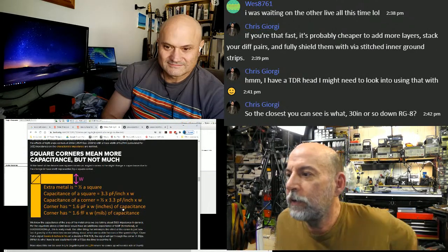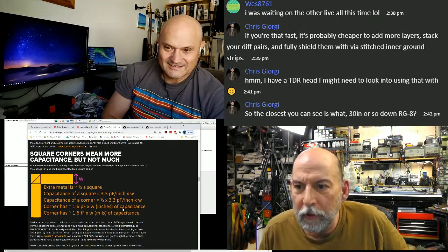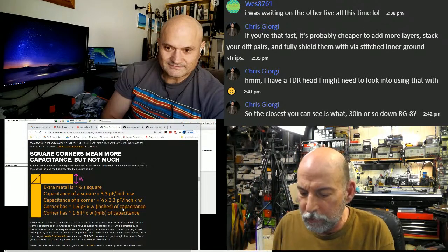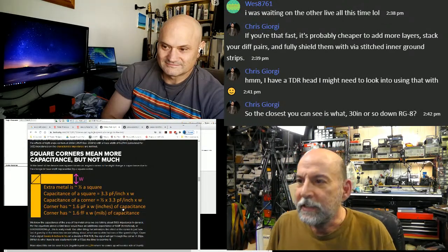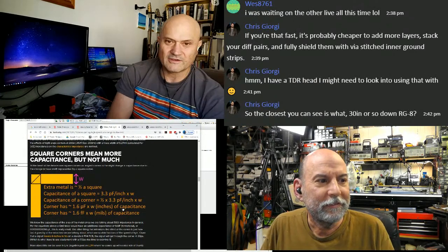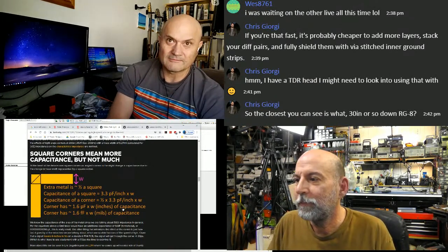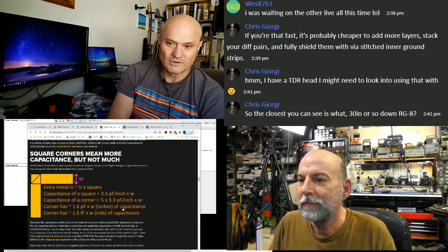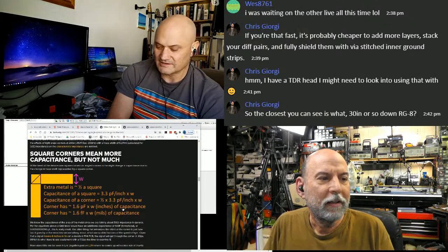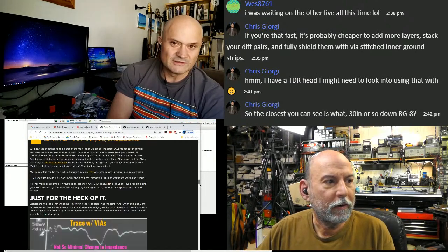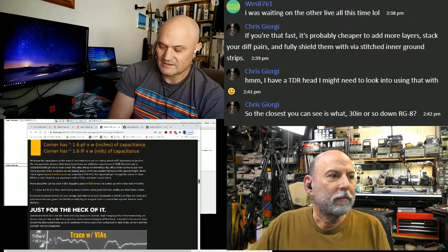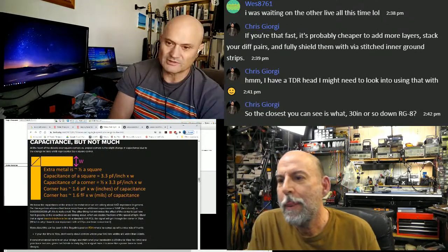Corners. So the thing about right angle corners, people go, and I saw somebody do this to Lamore from Adafruit. They're like, oh, you used right angle corners on your IO lines. Guys, it doesn't matter on your IO lines. For digital, it's only something you care about for RF, where you're not dealing with pulse type waveforms. You're dealing with modulated sine waves, and any reflection is lost, and you can use these structures deliberately to create transmission line filters and things like that. But you have to be intentional with everything you do with RF board design.